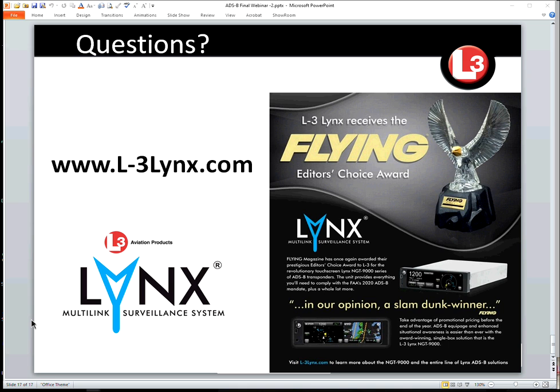Now, when it comes to the software, you would actually use a software tool on a laptop computer to load the device with your information and program it. And they can actually do that via Wi-Fi. Since the device is Wi-Fi enabled, you don't even actually have to connect a cable always to the device. You can if you would like, but you can actually get into maintenance mode via laptop just sitting in the cockpit or near the cockpit with the device on. So it would be a little bit longer process than an avionics shop, but an astute aircraft builder with some electronics experience should be able to navigate it.